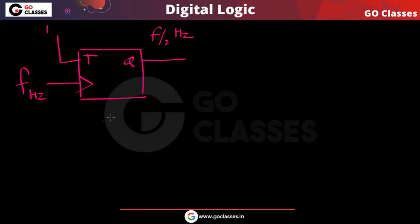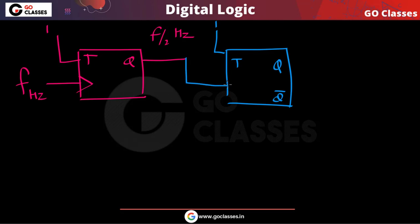Now the idea is very simple. Just apply this to another T flip-flop. Take another T flip-flop, and the clock for it must be this output. This is a clock which has frequency f hertz, so I can say this is your clock. The output of this T flip-flop will have frequency f by 2, so this output waveform has frequency f by 2.